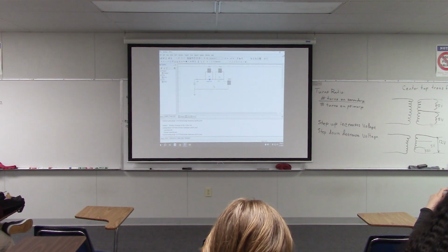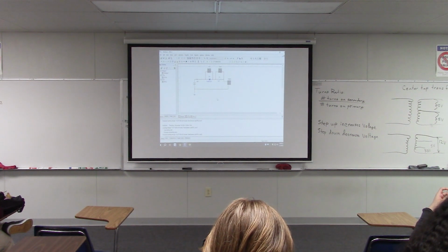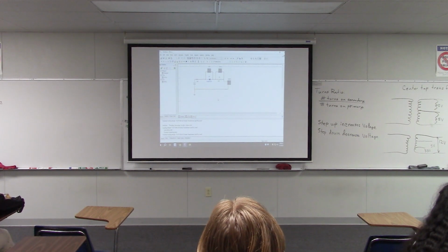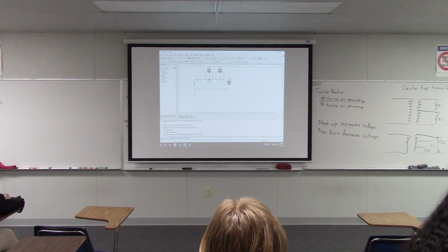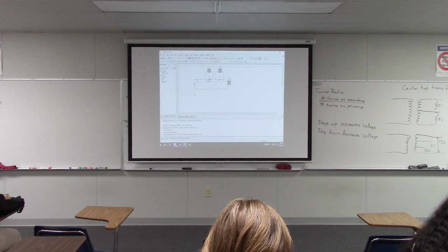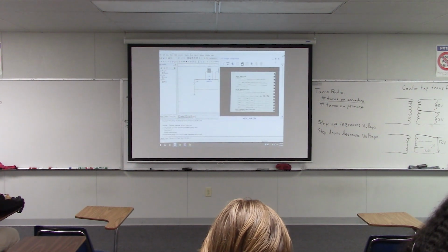Now this circuit is very similar to the first one, but there's one important difference. Anybody spot the difference here? That's right. The diode has been flipped around, so now it's reverse biased. So is there going to be any current flowing through there? No. Right.